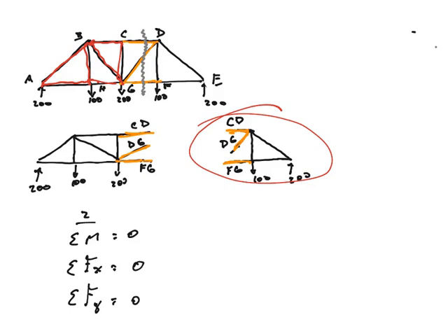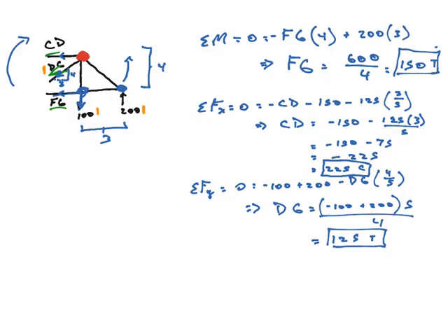However, if the three members we have of interest happen to be lined up in such a way that we could cut our truss along those three members into two separate, independent pieces, then we could bypass all that stuff and just use one of the pieces of the truss and do global equilibrium on it and figure out our three unknowns from there. Very, very nice technique that lets you save a lot of time if you don't care about the whole truss, you only care about specific parts of the truss.